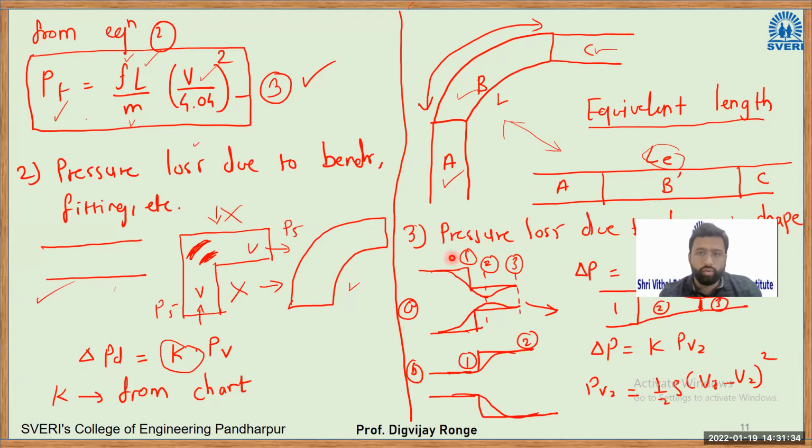If you want to calculate the total pressure loss, in that case, this curvature is replaced by a straight duct. So in the tables, there are some tables for this case, we'll get equivalent length value. You just have to give which type of bend it is, 45, 90 degree, and it will give you the equivalent straight duct length value.